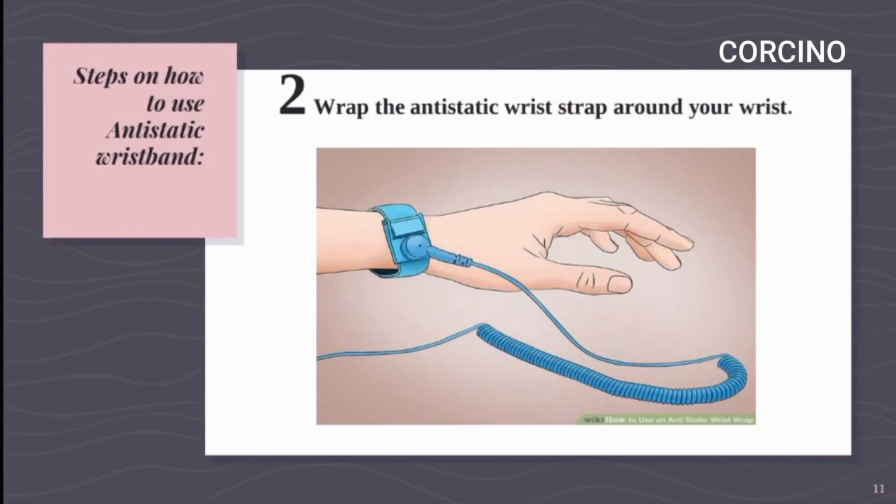Second is, wrap the anti-static wrist strap around your wrist. Before you come into contact with ESD sensitive items, put the ESD strap around your wrist and snap it closed. All parts of the strap should be in direct contact with your skin at all times.